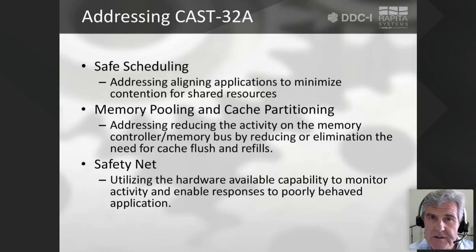Here are the set of features that address CAST 32A concerns related to interference patterns and shared resources in the Deos environment. First, we have our safe scheduling. This is a bounded multiprocessing feature that allows the integrators to align the execution units, the threads, the 653 partitions or POSIX partitions, to minimize shared resource contention.